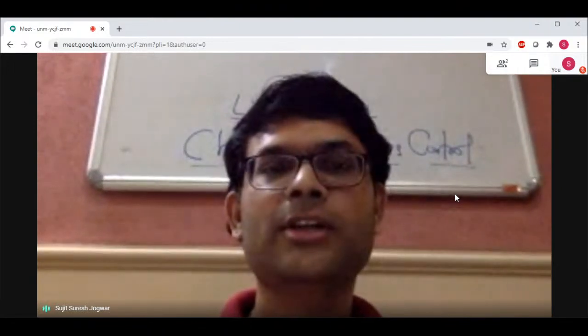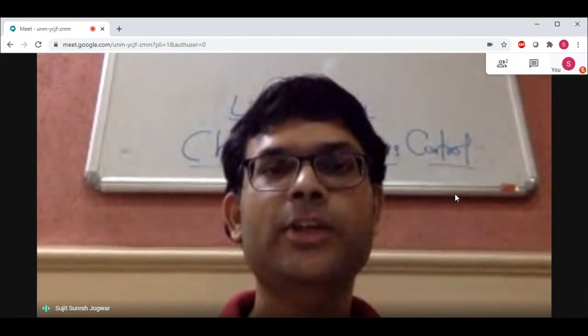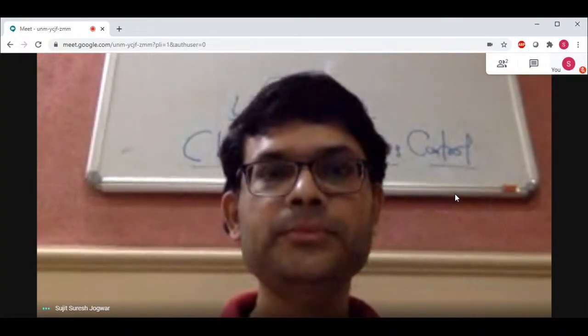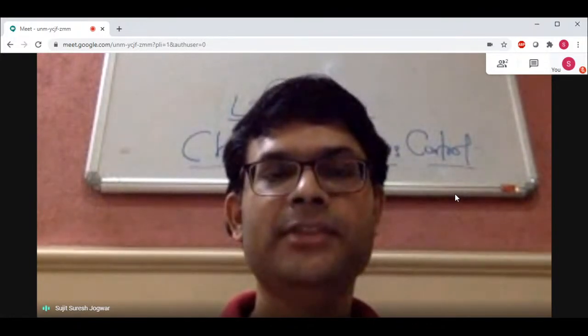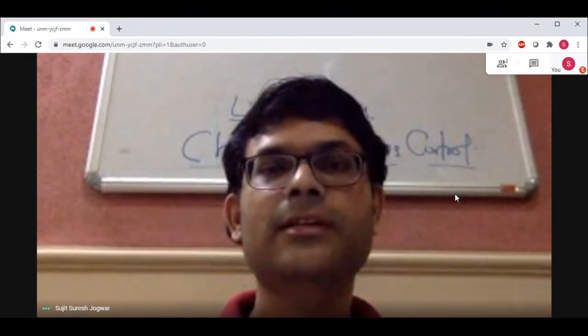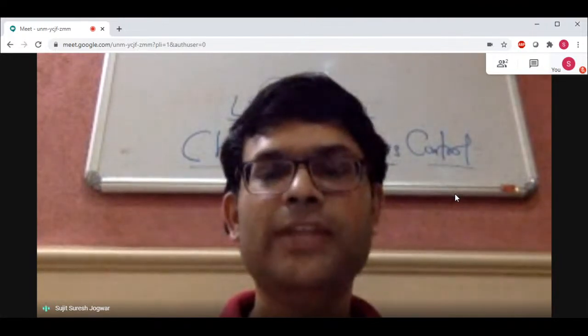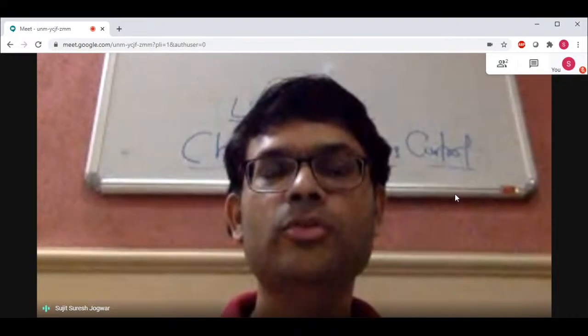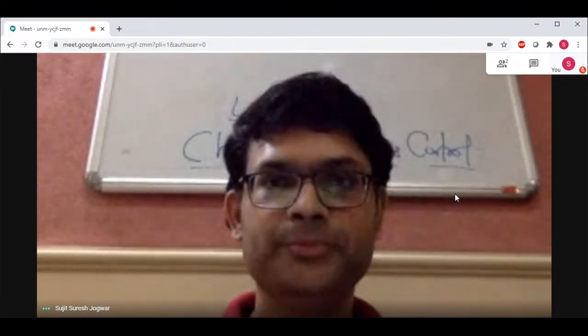If the zero is at 0, that means the numerator polynomial is simply s. Let's say your transfer function is s over (s plus 1)(s plus 2). In that case, the zero is s equal to 0. So that system will always go to the origin, and the final value of that system will become 0.